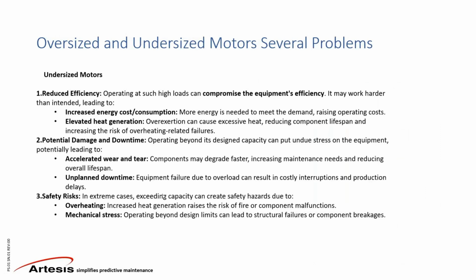So immediately the motor will become more inefficient, because a lot of energy will be converted to heat dissipation. And this heat will not just make the motor less efficient, but excessive heat will also reduce the component lifespans, including the stator windings and other components inside the motor.